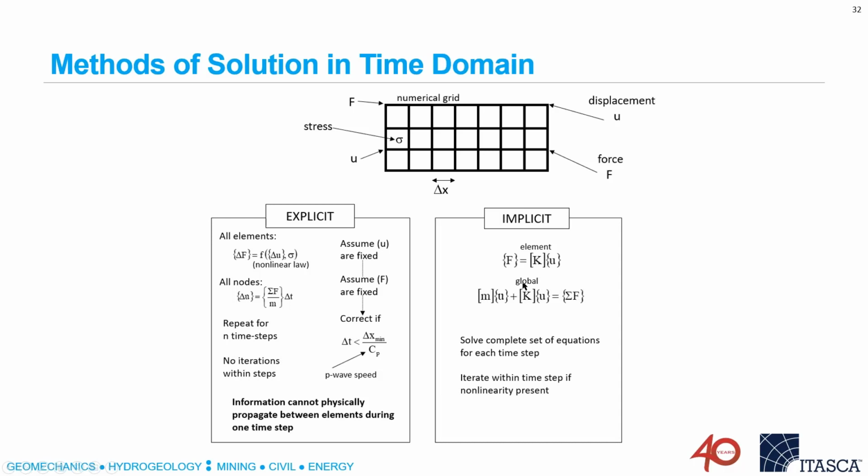This happens to be for dynamic analysis, but it would look exactly the same for static analysis. You just have a large system of equations that has to be solved for each time step. And if there is any nonlinearity, you have to iterate within that to make sure everything satisfies all of the compatibilities of strain and displacement. So that on the right-hand side is